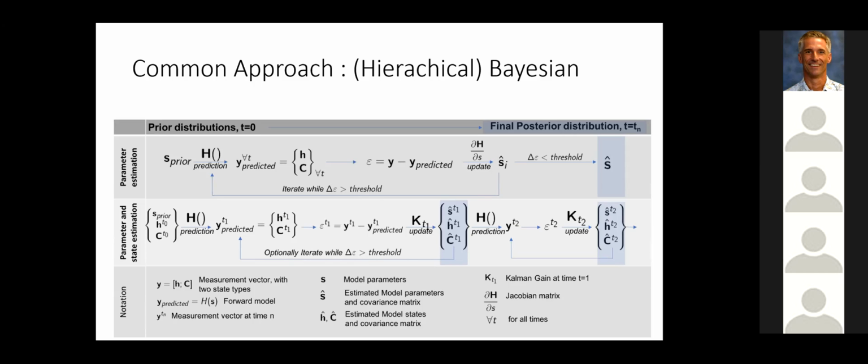Second, the soil type at one location is very correlated to the neighboring soil type. So you may assume some kind of spatial correlation between 2 points or 3 points or other points based on their area. This kind of information can be encoded in your statistical model, starting with this prior information, and you can update with the observations, then you will get the final solution. And data assimilation is basically the same, but there is a stream of data you update over and over, mostly for forecast and also estimation of underlying parameters.